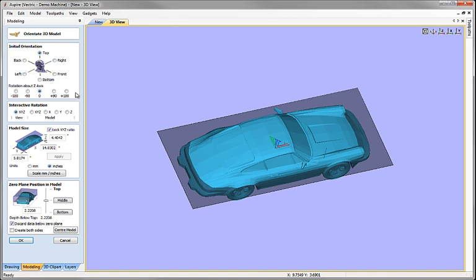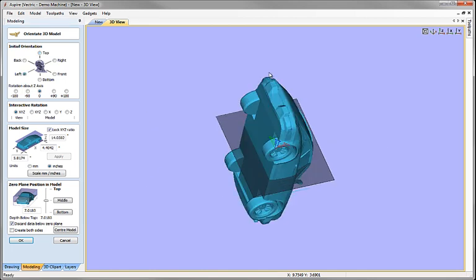Now we can choose one of the standard directions in order to start our orientation process. At the moment it's oriented so we're looking down on the top of the model. These words just represent directions on the model in the way that it was actually saved. They have no concept of the fact that the car has a top, bottom, left and right. In fact, in this case, the left of the model would actually be looking at the back of the car. If we click on that, you can see the back of the car is now oriented up.